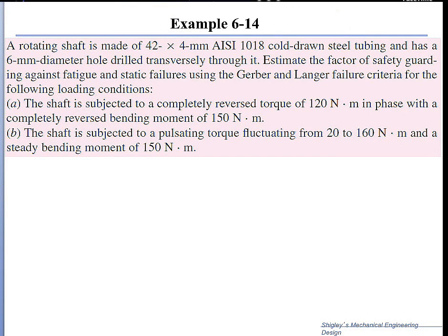And it has a 6 millimeter diameter hole, so A is equal to 6 when we look for stress concentration factors. In this case, we want to estimate the factor of safety, guarding against fatigue first, and then second, guarding against static failure. And we would like to do that using Gerber and Langer failure criteria.